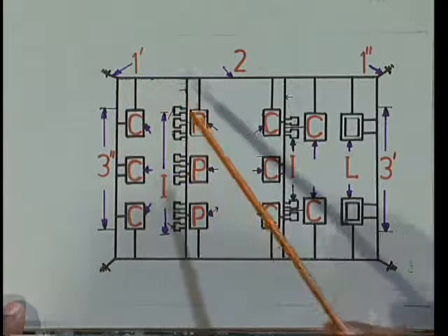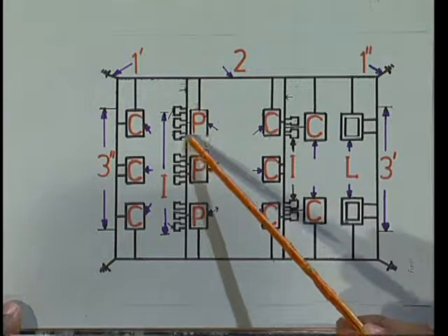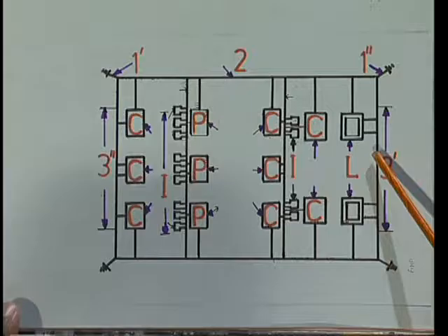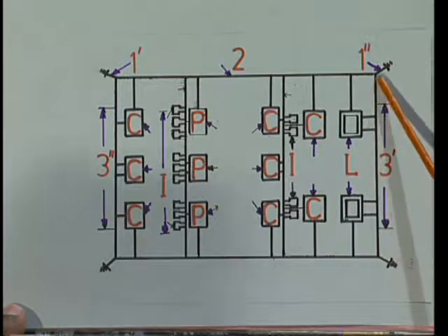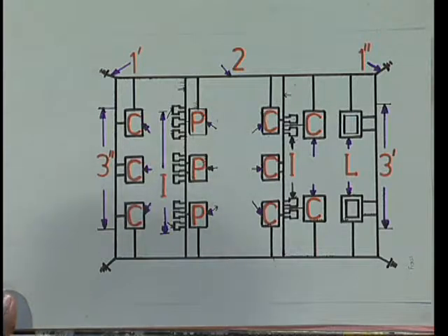It will always choose the lowest distance path. So it will go through the shielding network and discharge. That means it will protect the power system equipments against directly hitting the substation or generating station equipment. In this way we protect the generating station or substation equipment by providing the shielding network.